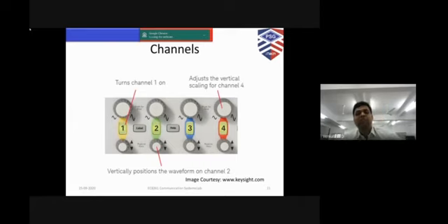Okay, and also these buttons are not only potentiometric buttons, you'll have a push button at the center. If you push the larger potentiometer, it can do fine tuning. If you push and then tune, it is for fine tuning of the vertical section. And if you push this button at the center, it is pushed to the ground level. Normally in the CRO, we have a button which we push, and it will stay at 0 voltage, and you have to tune it for the ground level. Here, if you push it, it will automatically detect the ground voltage and move accordingly.